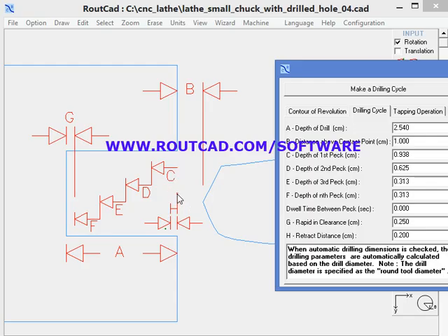In this case, we put a point right there at the surface of the workpiece, and the distance above the contact point is how far away our drill bit is located above the contact point. In this case, it is located 1 centimeter above. So when we start that operation, the zero of our CNC is 1 centimeter above the contact point.